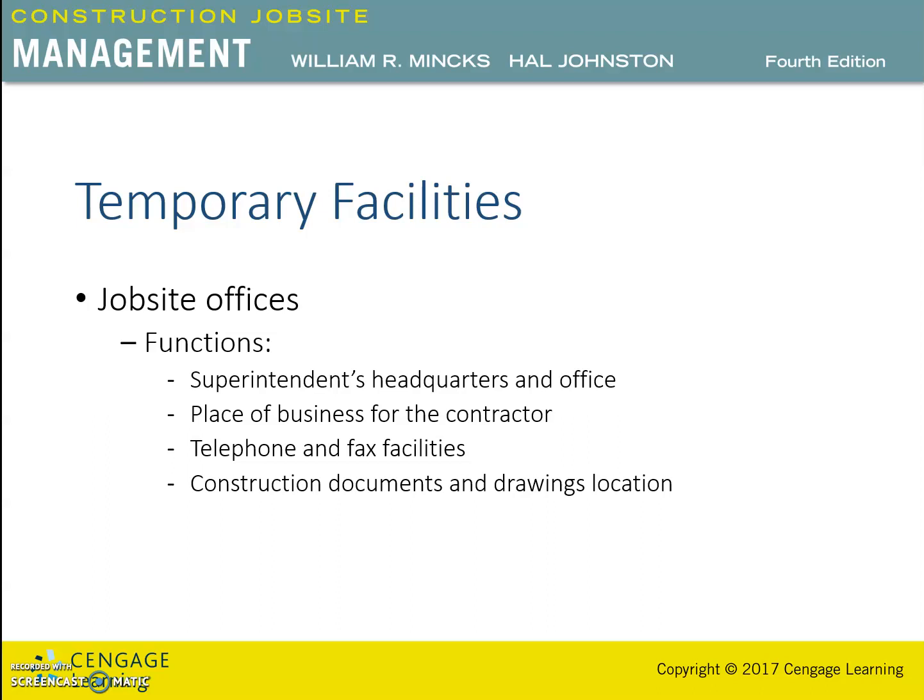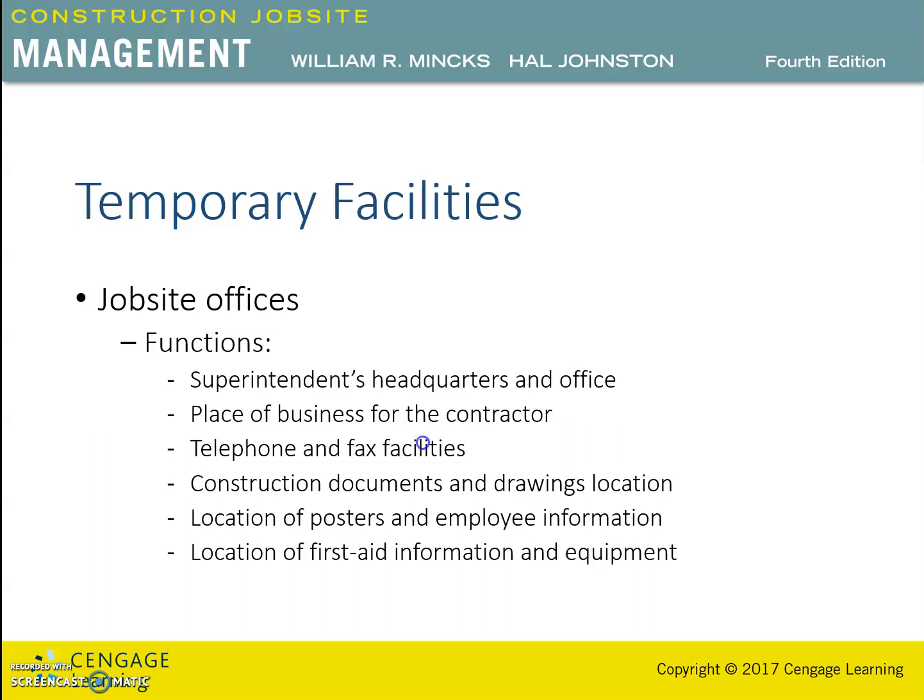It is also a location for the full and current set of construction documents, including addenda and changes. Most contract documents require that the contractor keep a complete and updated set of documents at the job site. It is also the location of the record drawings, or as-built drawings, which show the actual dimensions and locations of the project as constructed.